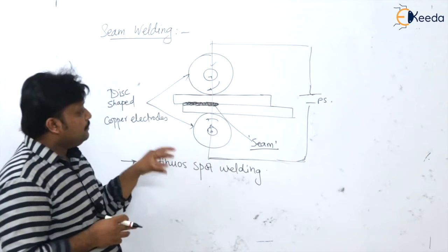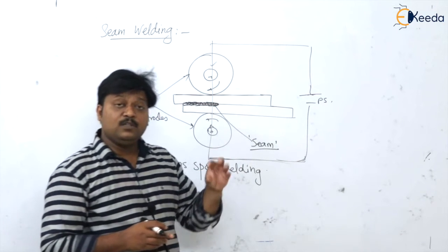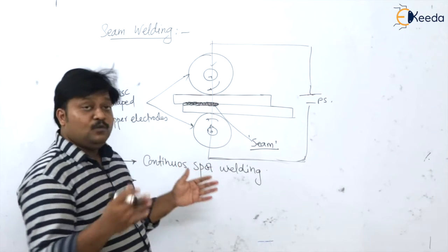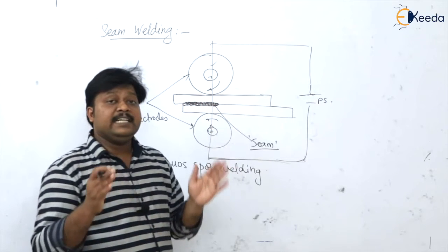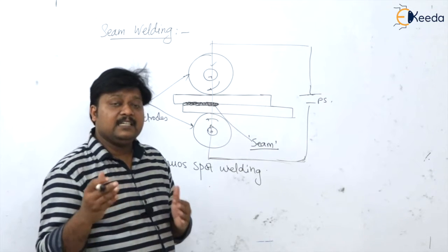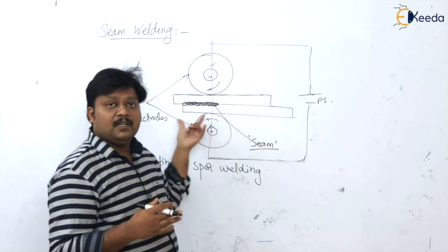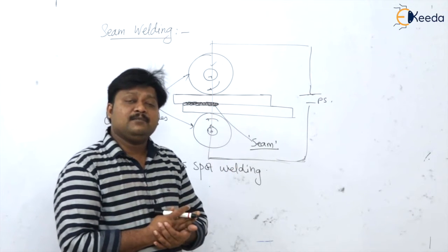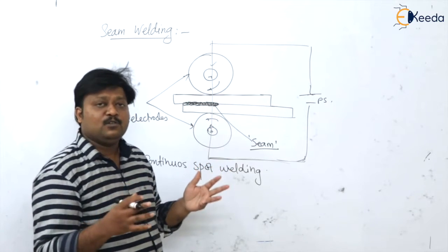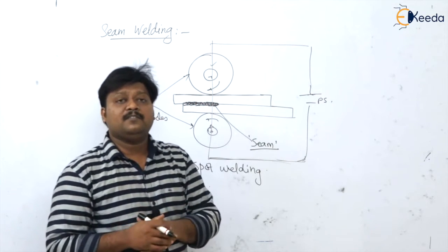We slowly go on increasing the current conditions up to a distance of 48 times T, until the length of the seam reaches 48 times T. Whatever shunting is going to happen will finish, and then we apply the required amount of current.